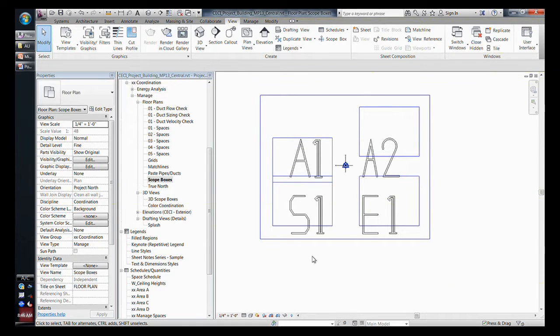So here is how I approach this kind of challenge. How many levels do you add in your template? How many floor plans, right? I've done it up to 5 levels, and up to 4 scope boxes. New project starts. We're getting a high-rise, 10 stories. I don't go to set up the project. I go in my template. I keep working on this, adding the levels, adding the views, applying the view templates. Now what happens? My template is 10 levels ready, okay? I start the project, I'm done.